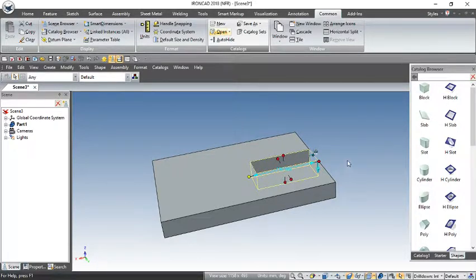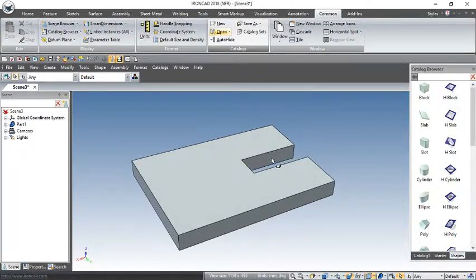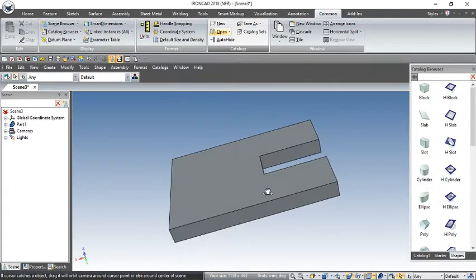That's 100 long. If you want to move these shapes symmetrically, pick one handle on this side, then press the Control key, and keeping it pressed, hover over and select the opposite handle and drag them like this. You'll see that they automatically move symmetrically to one another. So that's quite a useful tool.